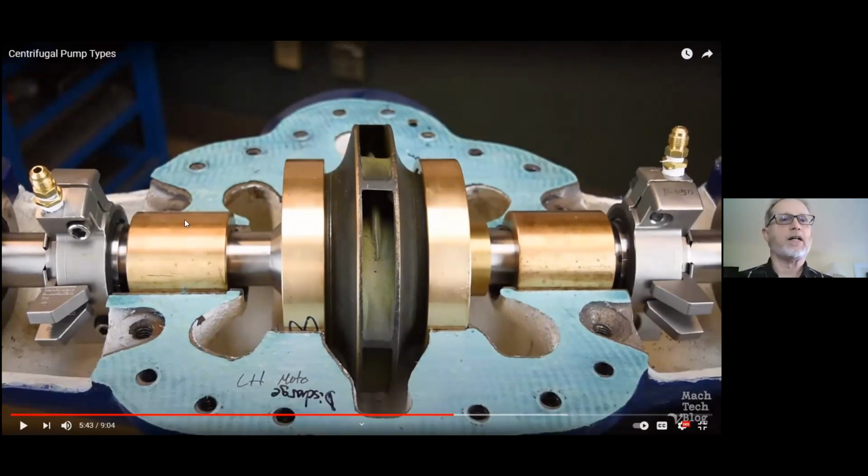And you can see here a couple of things. The volute, and you can see the shape, the wear rings. And so the wear rings are tight fitting between the volute and the impeller. And because it's a double-ended pump, you've got two wear rings so that water being pulled into either side, we've got the same close tolerances. And the wear rings are, you can see, made of an alloy or bronze. And they are meant to wear in advance of the actual casing.